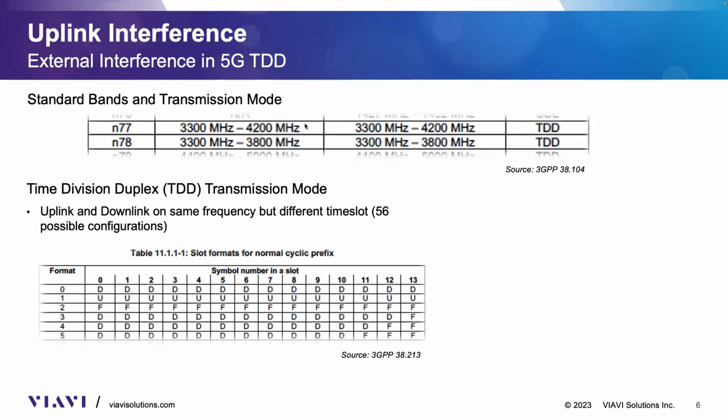If 5G is deployed in the low bands, let's say below 2 gigahertz, that deployment is going to be frequency division duplex, or FDD. In essence, that's going to be very comparable to LTE. Now, if it's deployed in the mid band, certainly everything above 3 gigahertz, all that is time division duplex, or TDD based.